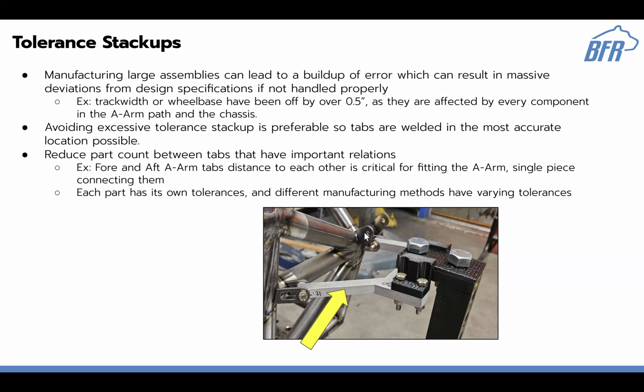But yeah, also keeping in mind which manufacturing methods are being used. They'll each have their own varying tolerances. If you ask the makerspace about certain printers, you can look up their general specs of tolerances, versus our water jet parts, which might be like 10 thou off for overall profile. So that's all stuff you can take into account when designing these.